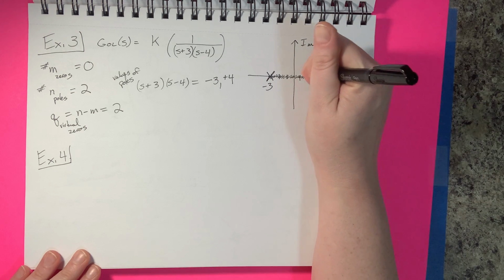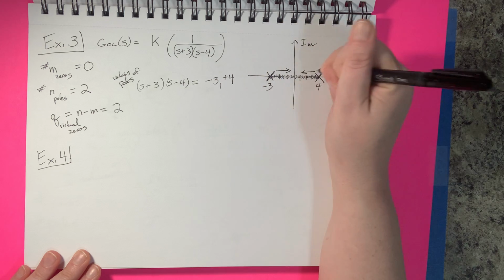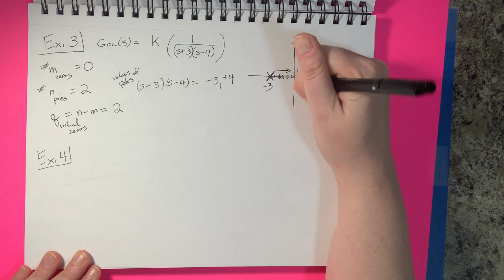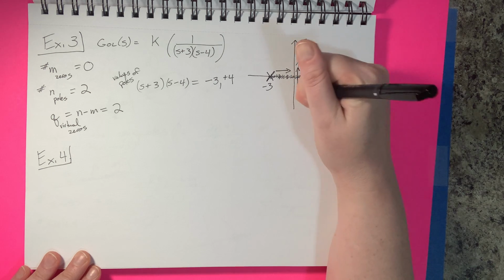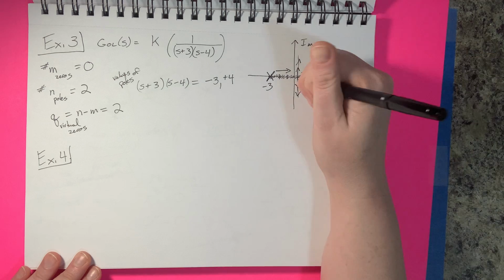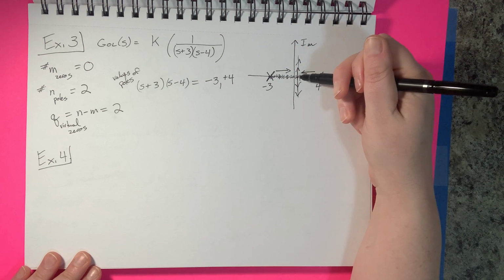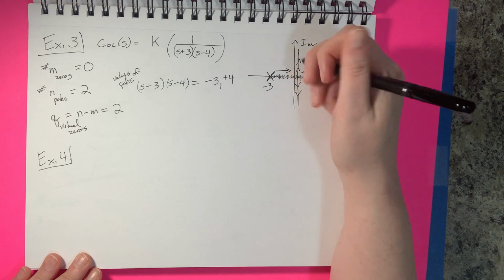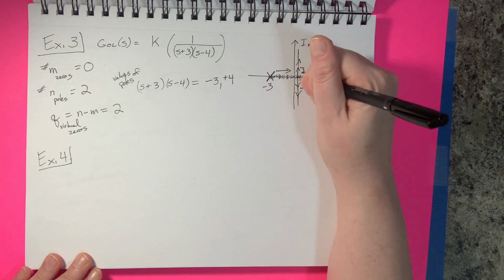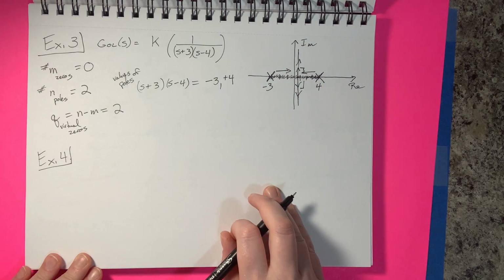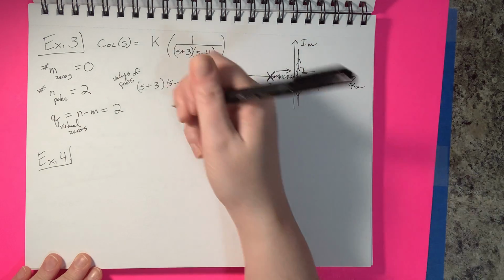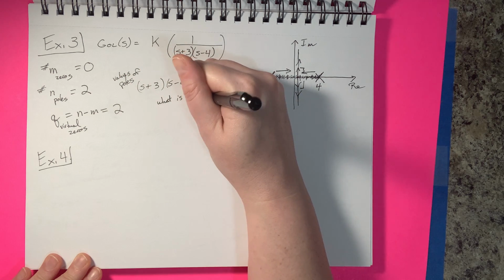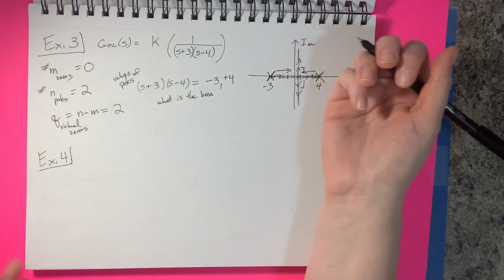So what happens is they move towards each other, and there's gonna be some point where they break out. Some point, maybe like right here. I'm just guessing right now. We haven't actually solved for this. But whatever K value that is, they break out and they ricochet in plus minus 90-degree directions to their original movement. All right, let's figure out what that point is. That is the breakout point, or breakaway, or break out, break in.